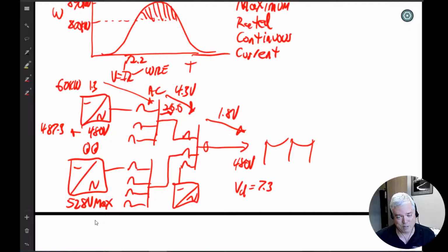So what would happen if your voltage drop was out of control on a large system? This has never happened to me, but I've heard of this happening. What would happen is you get a phone call in June, July, maybe August. It's a nice bright day out, but it's not super hot. It's in the 90s, very bright, and you get the dreaded call that says our inverters are shutting off. We have a string inverter system, 1.3 megawatt.